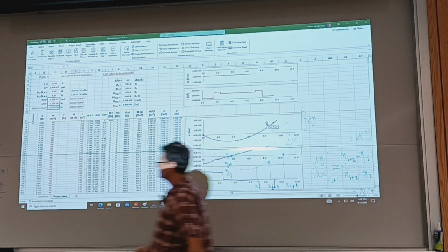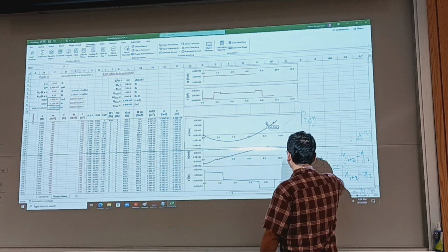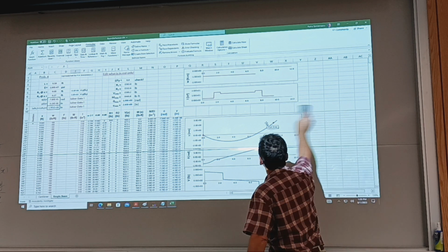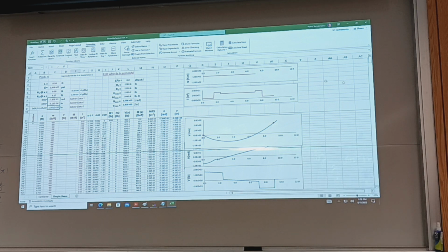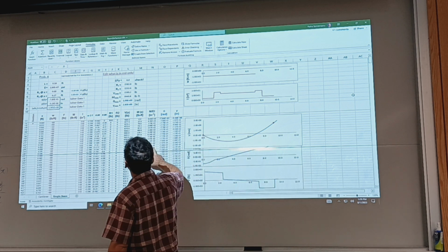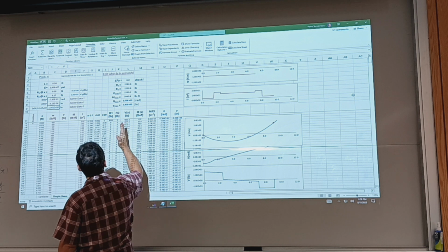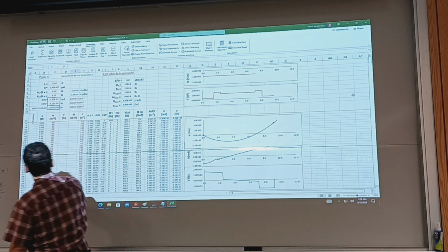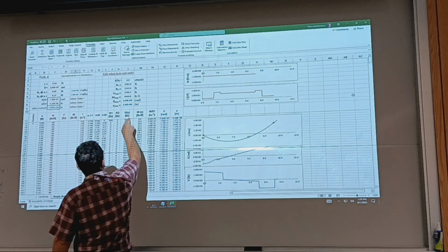And actually there's a document that explains how to use Goal Seek in Excel. But right now I'm pointing out the need for reconciling some constants of integration. So really the way it goes, it just does successive integration. All right, so I get V by adding the concentrated forces and then integrating the distributed load. I get moment by integrating this.